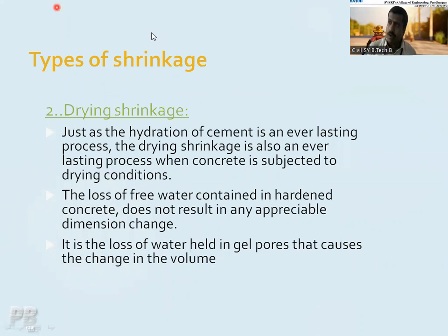And what happens in the drying shrinkage due to the change in the weather conditions? There is a loss of water from the walls, or from the gel pores. If the water is evaporated from the gel pores, what will happen? If there is a loss of water from the gel pores, there is a change in the volume of the given concrete.